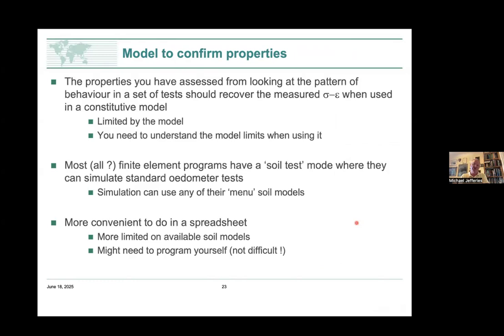We need to contemplate modeling. Now, keep in mind, when I showed you the plot of strength versus the dilatancy, you could say, well, that green line could have been twisted a bit. Why did I choose an M of 1.26? Maybe 1.28 would have been a better choice. And if I chose a 1.28, then N instead of being 0.35 might have become 0.33. So that's a very reasonable thing.